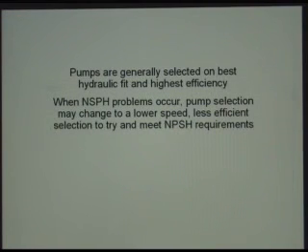The other thing is, generally, we try to pick the best hydraulic fit and the highest efficiency that we can get for the service. There's a lot of pump manufacturers out there. They have all kinds of different styles of pumps. We can usually find one that's got a pretty good fit efficiency-wise and flow-wise. But when we have an NPSH problem, we may change our selection to a lower speed pump, which will run less efficiently, but it will meet the NPSH requirements.